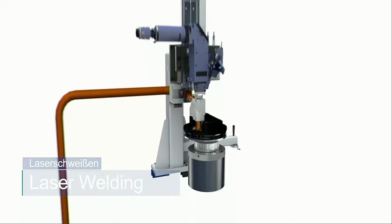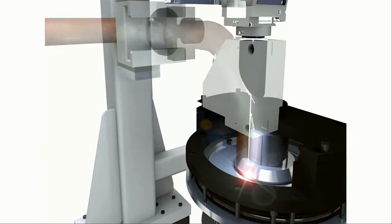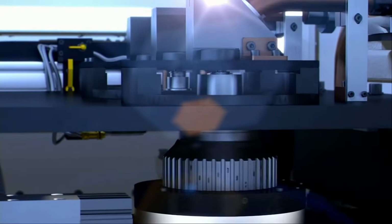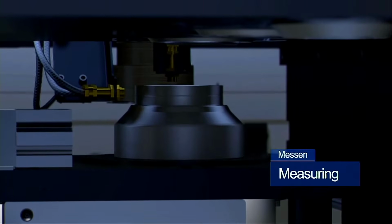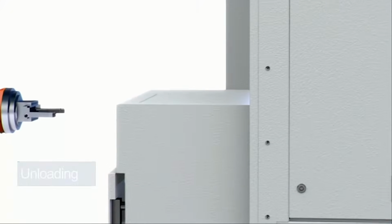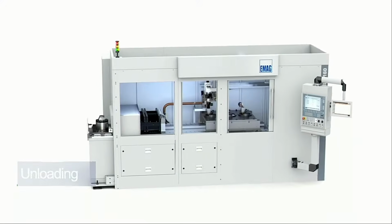Here, as in most of the welding machines of EMAG, the idea is to have a moved workpiece, so a turning workpiece. The optics is fixed. The workpiece is completely covered during the welding process, so we make sure that there are no spatters on the workpiece surface itself. And then we move the workpiece to a next position. Here we have implemented a sensoric to measure or to control the runout.